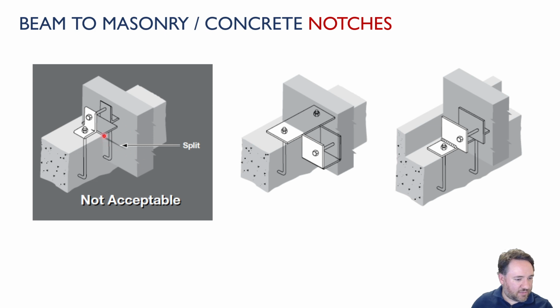I can look at my shear resistance for tension notch fracture, and I can find the strength. But you remember when we talked about tension notches and fracture shear, we get a really big penalty for designing our beam this way. So we're going to have a very low shear strength if I design it like this, and that's a brittle failure condition as well. So it's definitely not ideal to design a timber connection that looks like this. You'll see we're still providing the steel plate to provide a moisture break between the concrete and the wood. So what's a better way? Bearing is always a better way to transfer load in wood than direct shear.